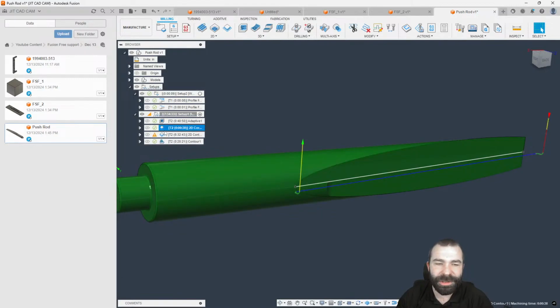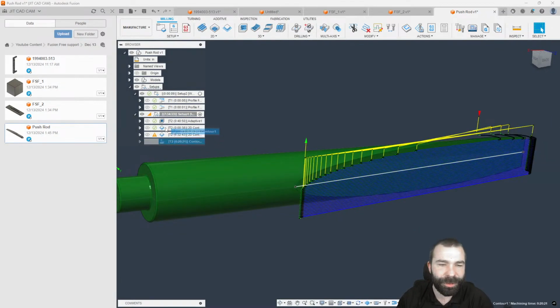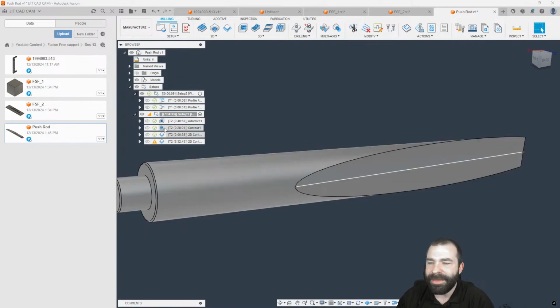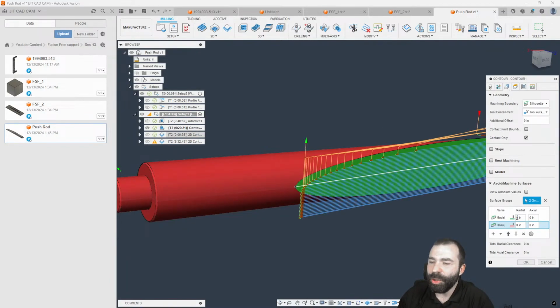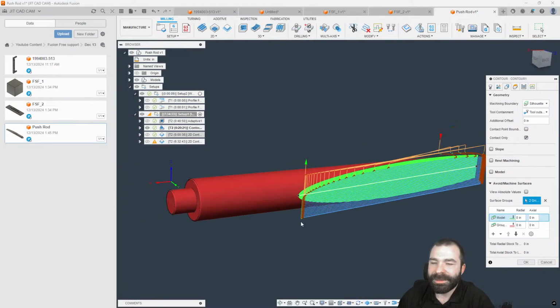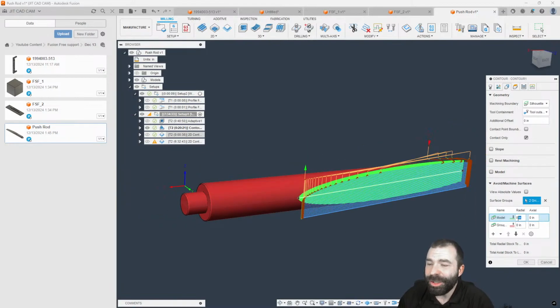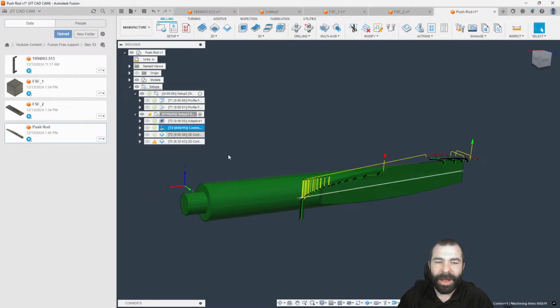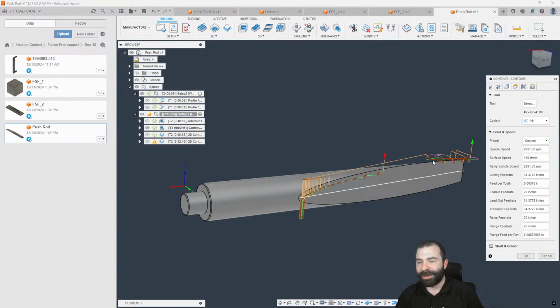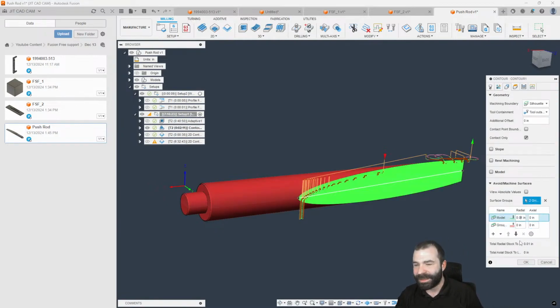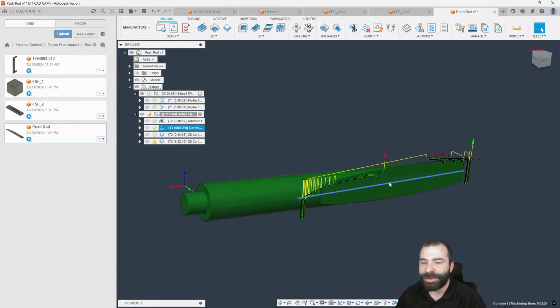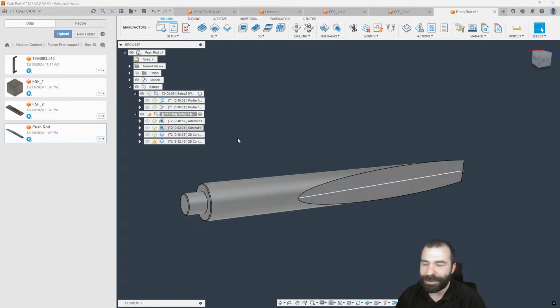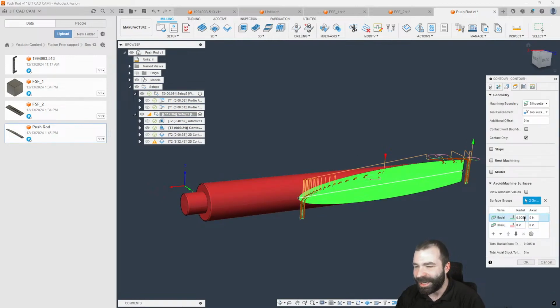Now, based on your toolpaths, I'm actually going to have to do this with 3D, in that toolpath you can actually avoid a surface. So what I could do here is radially add 10 thou to specific surfaces when machining. Now, I don't know how simple or hard your parts are, of course. Let's go ahead and go back and fix that one more time. So let's bump that down to about 5 thou. We should be able to machine that surface.